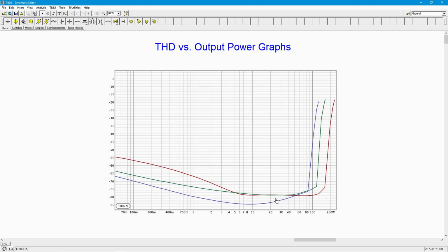Well, the question is, how low is low enough? Well, I want to point out something, and that's minus 60 dB. Minus 60 dB is a factor of 1,000, and that would correspond to 0.1% THD. Now, you will hear people say, that's a terrible number for hi-fi. It has to be 0.00000000000001. Insane numbers, right? Golden ears will tell you these things. Oh, it's got to have at least 3 zeros up front.